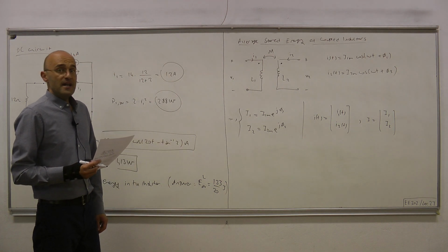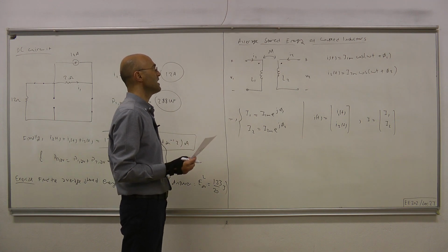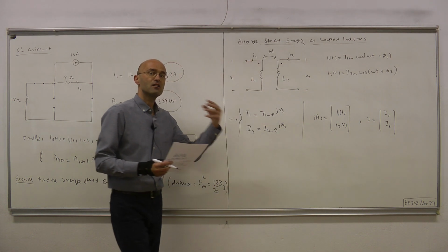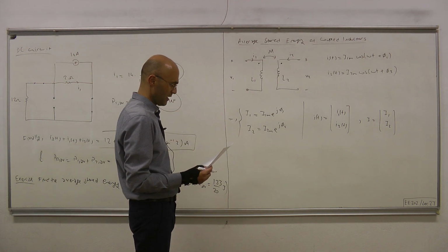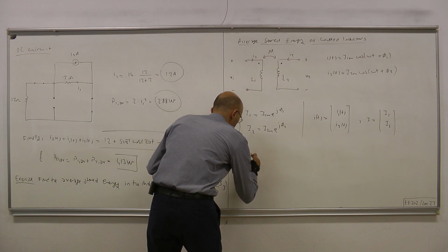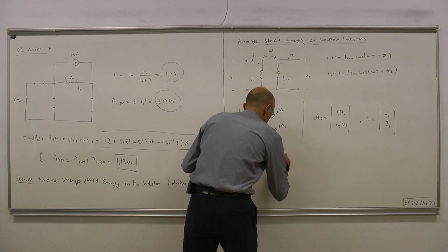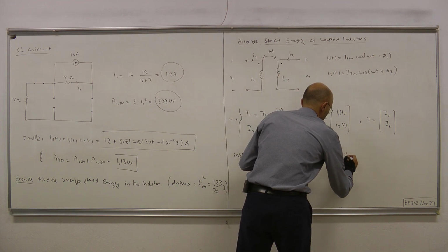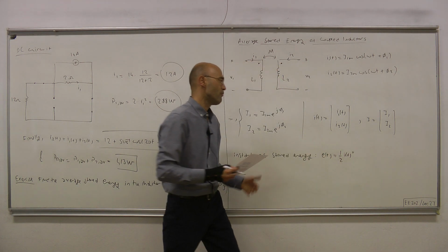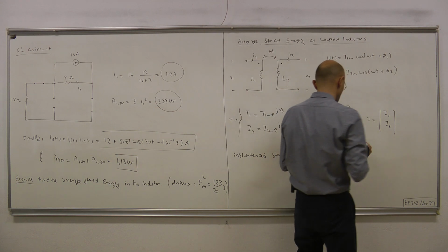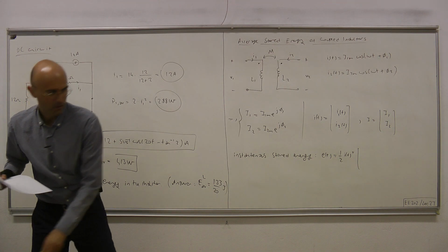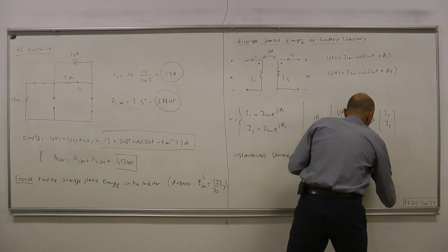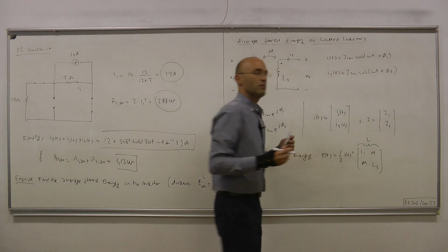Now, we have already obtained the instantaneous stored energy in a coupled inductor, and we had a very nice compact formula, which was 1/2 times the transpose of the current vector times the inductance matrix times, once again, the current vector. So instantaneous stored energy reads E of t equals 1/2 I of t transpose. Okay, so that's a row vector multiplied by the inductance matrix. Okay, let me write it down: L1 M, M L2. So this is our inductance matrix, times I of t.